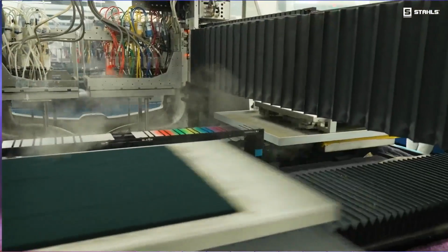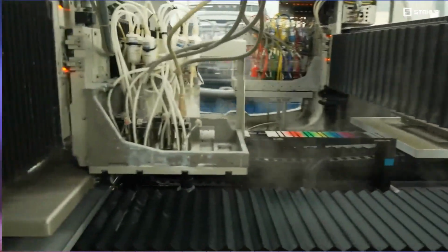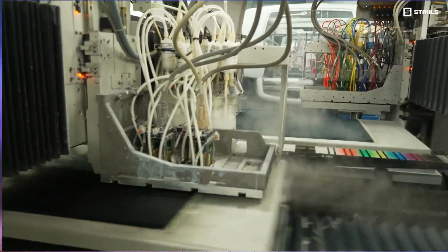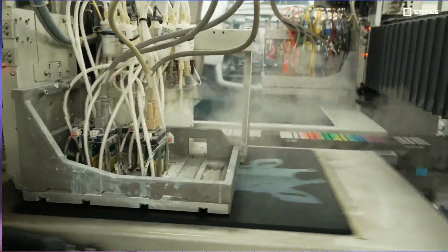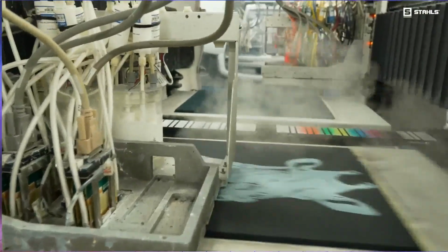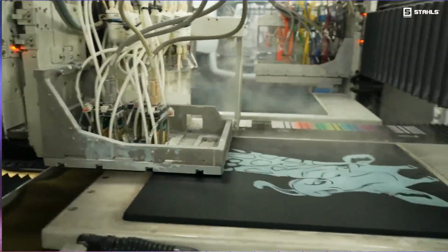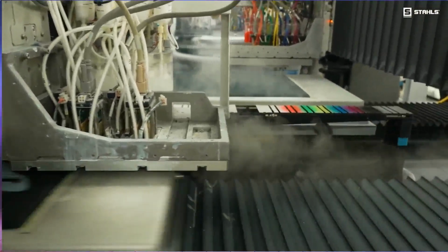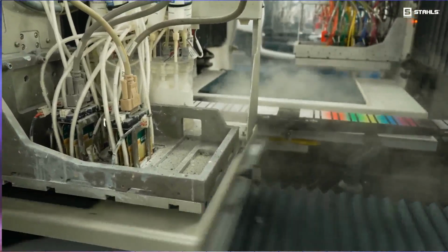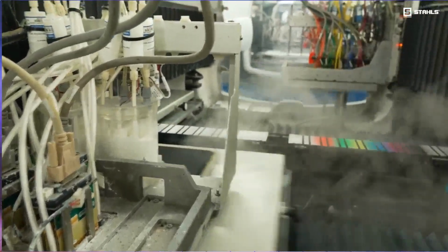Now, something that you see here, these machines are printing. What they do need to do is pre-treat the garments. These machines here are doing it in the back of the machine, it's all enclosed. But the smaller machines, the Brothers and the Epsons and a lot of the smaller machines that we have in our own shops, you have a pre-treat system that is separate, okay? So that's stage 1, pre-treat the actual garment itself, which is just putting a solution onto the fibers of the garment that's going to help the ink bond.